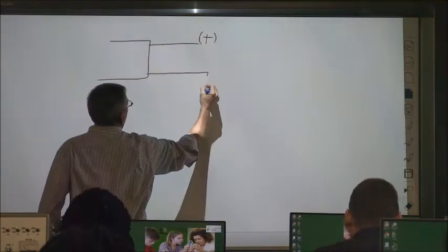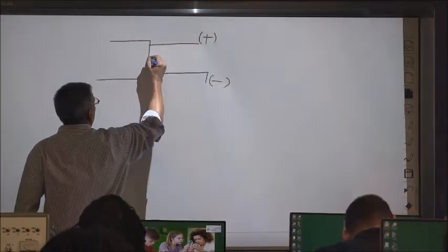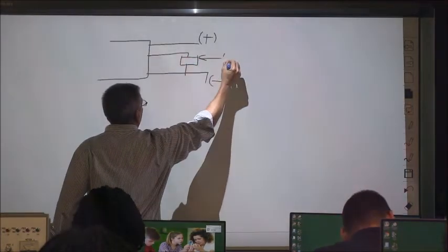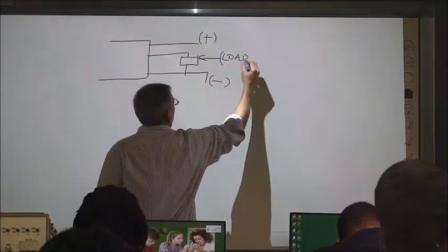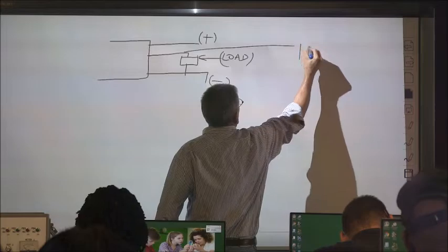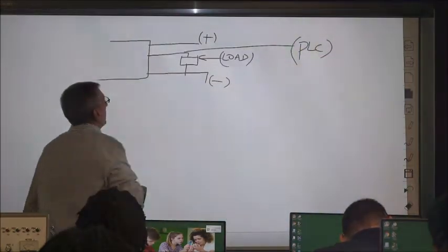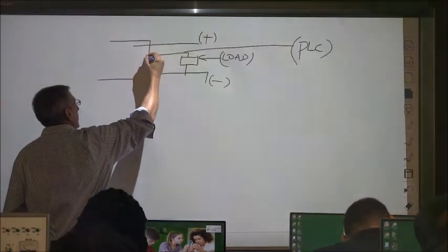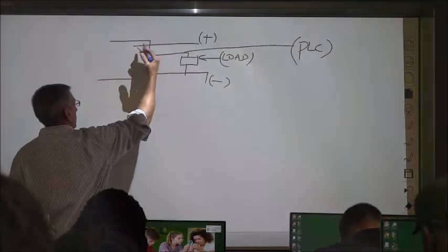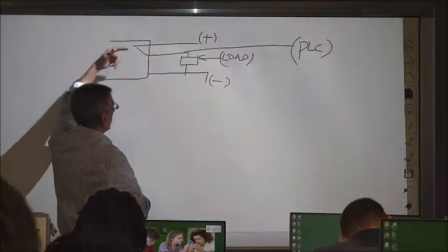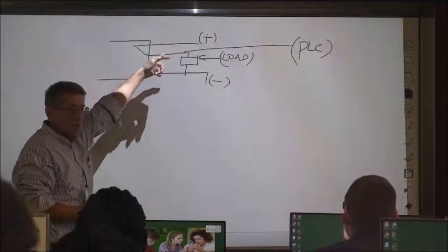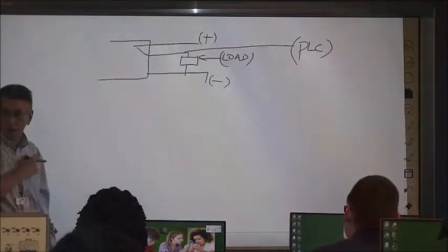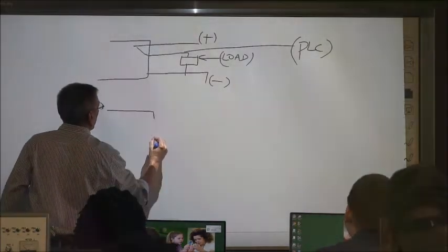it's something like this. 3 wires. This is the load. In our case, this output would go to a PLC. And what happens when the proc switch is made, it's basically taking this load to it's like a switch inside. It's connecting the load to the power, to the positive side of the switch. Yeah, it's activated. And then a 2-wire,